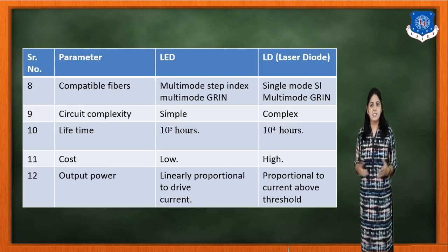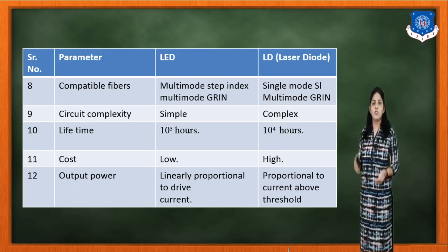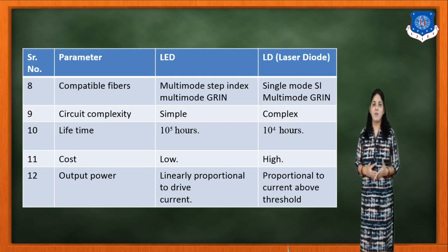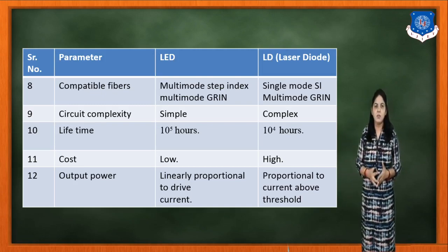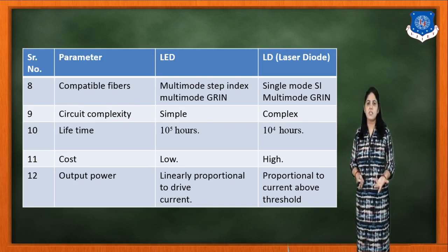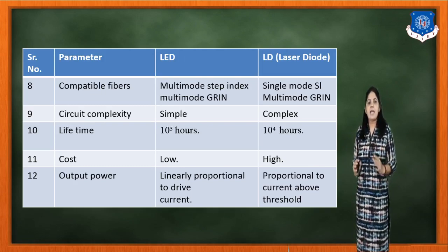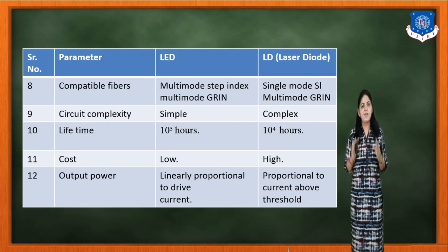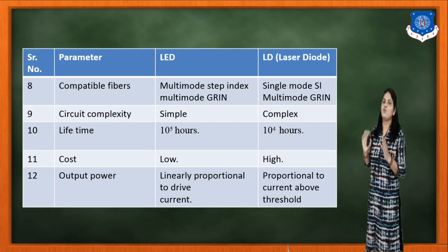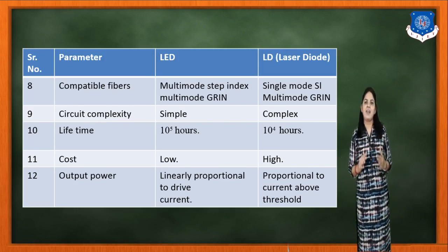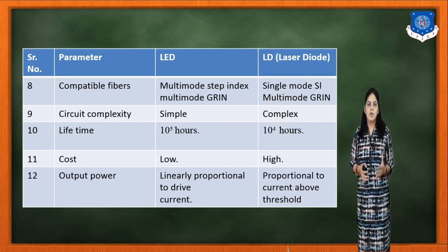In the case of the laser diode, single mode step index and multi-mode graded index fibers are more compatible. The complexity of the circuit using the LED is simple, and using the laser it is complex. The lifetime of the LED is 10 raised to 5 hours, and using the laser diode it is 10 raised to 4 hours.